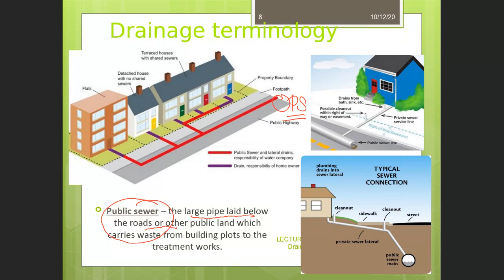We will go through this item after this. For the laying of pipe, yes, we have to first identify the item to be measured. Definitely you have to do excavation. But for the excavation for the drainage, there will be no backfill. That will be counted together with the description, including backfill. This is something different as compared to your measurement before.